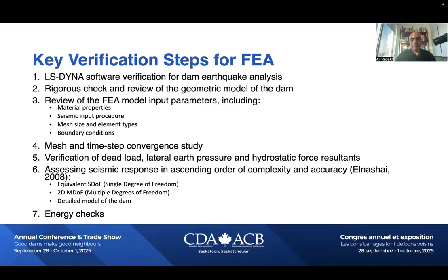For seismic response, we increase the order of complexity and accuracy, which we sometimes call progression analysis. We start with equivalent single degree of freedom, proceed to 2D models, and then we end up with detailed nonlinear 3D models. And we also perform energy checks.